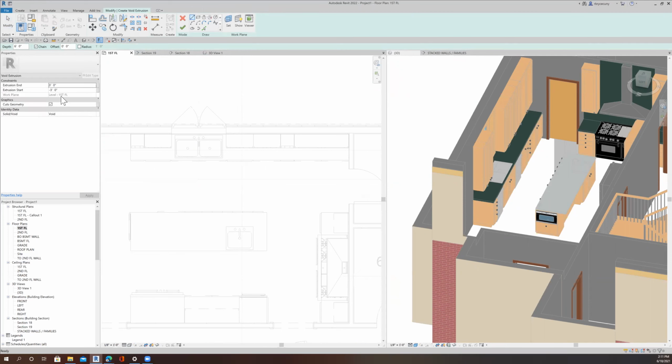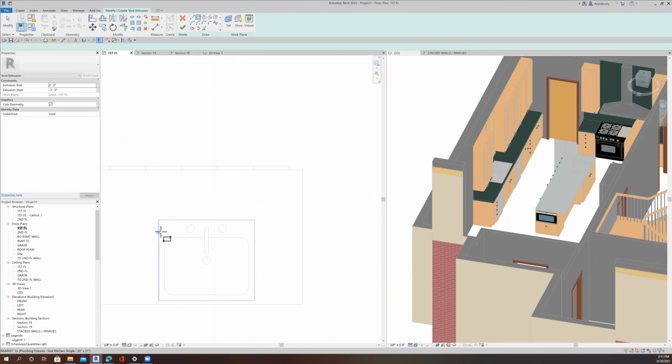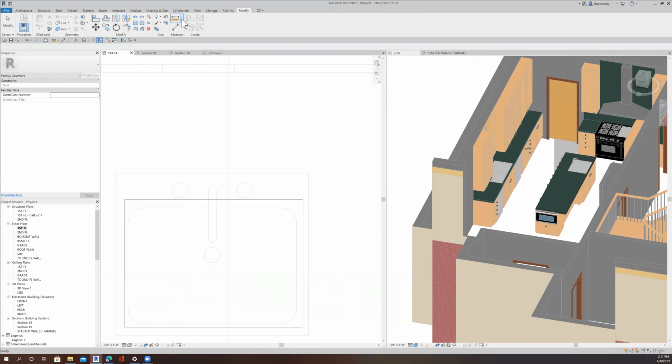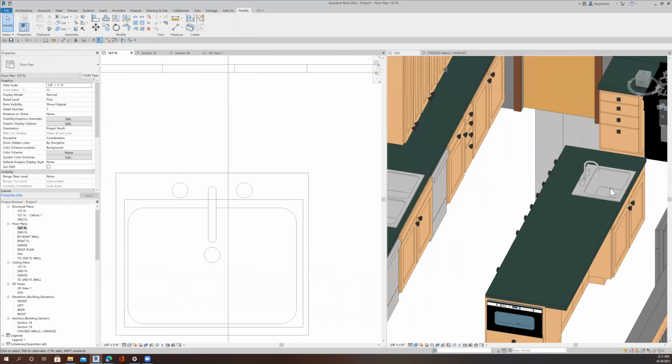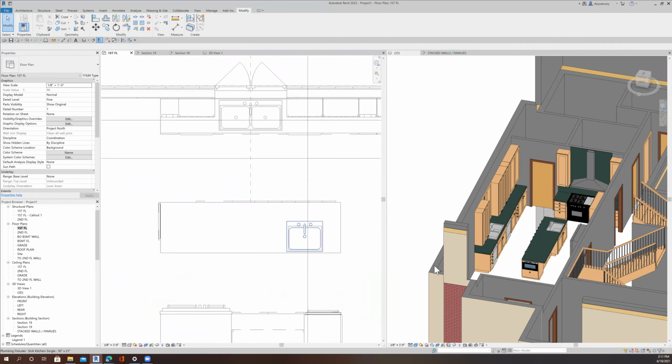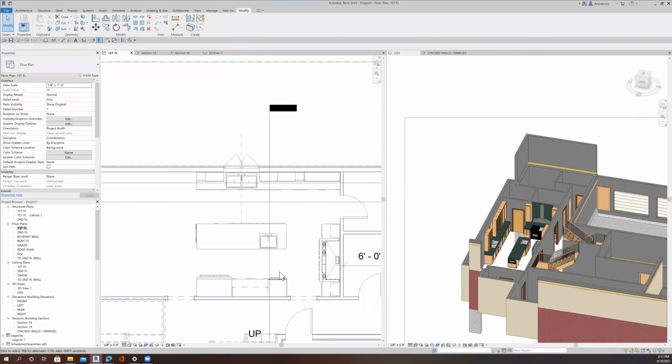That'll work too. Relative to the first floor, I'm going 3 feet up and 3 feet down, so the void is bigger than the countertop, which is fine. It'll cut through the countertop. It starts at the height of the countertop, but it goes all the way down to the floor. It doesn't have to go that low, but that's okay, it'll work. And just say cut. Let's see what happens. So if I cut it, look at that. Beautiful. Cut my countertop. Okay. I think that's it for this guy.